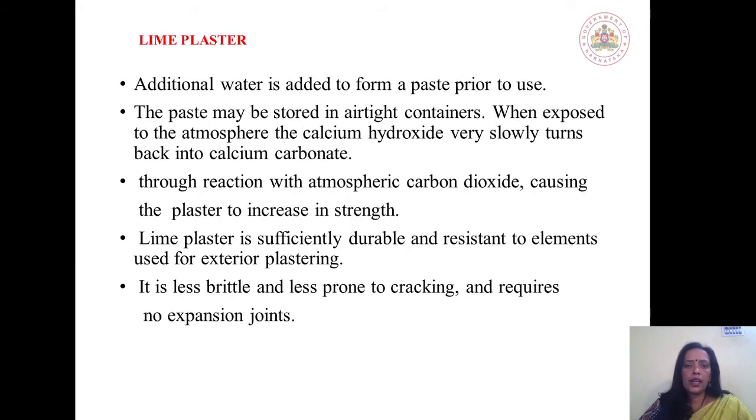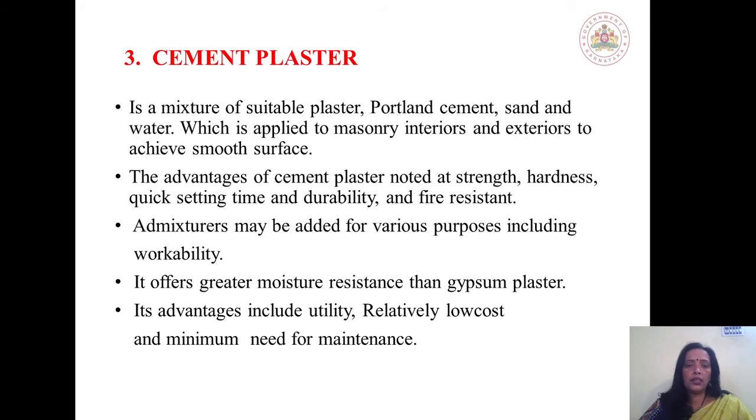Lime plaster, when it is added with the water, the reaction takes place. The lime plaster advantage is that it is sufficiently durable and resistant to elements, so it is suitable for exterior painting. Gypsum plaster is actually for the interior surfaces. The lime plaster can be useful for the exterior plastering. It is less brittle and less prone to cracking, and it requires no expansion joints. This is the advantage of the lime plaster.